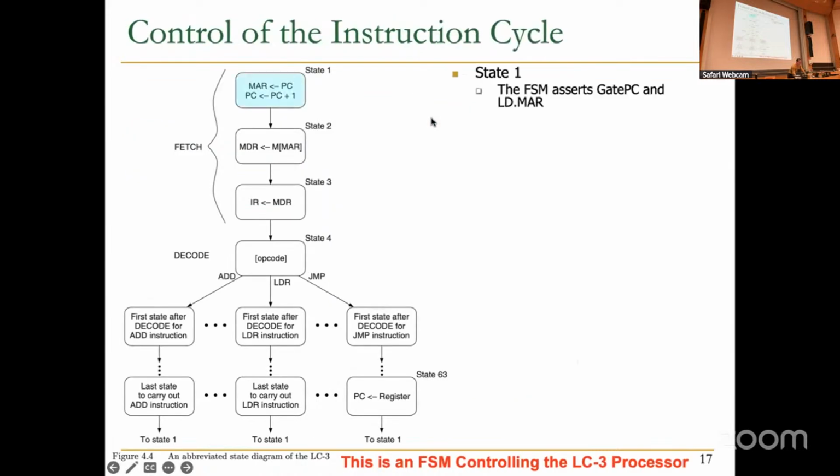And the reason why we increment the program counter by 1 is because we're kind of done with this instruction, right? Done in the sense that we fetched it. We're going to write the instruction to the instruction register. We didn't fetch it completely yet. We're going to fetch it in state 3. But we're done with the program counter. We took the program counter, put it into the memory address register, and we are going to fetch from that address. Now we should move on to the next instruction. So this is a design choice that someone micro-architecting the machine made. You could have incremented the program counter somewhere else, essentially, right?